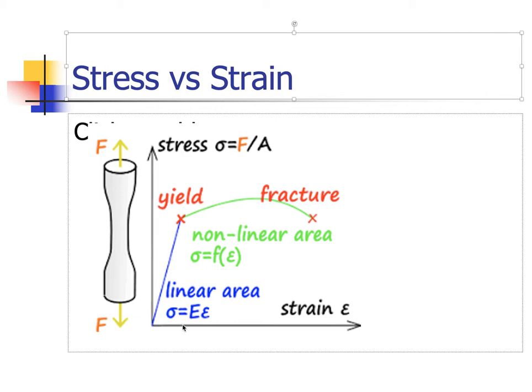And on the strain, it was 1 thousandth of an inch. So this strain here is going to be really small numbers. So let's say 1 thousandth of an inch is somewhere like here. Now what I told you is it was about half the distance before it actually started to fail. So it was 31,000 and the strength is 60,000. So it would be right about here on this graph. We would have this point. And if I put 2,000 pounds on it, we'd be right up here, right about where it's going to break.